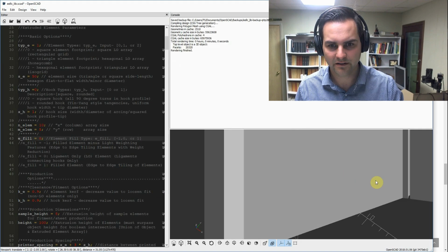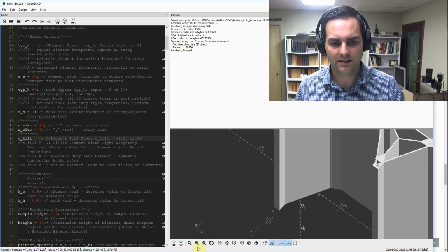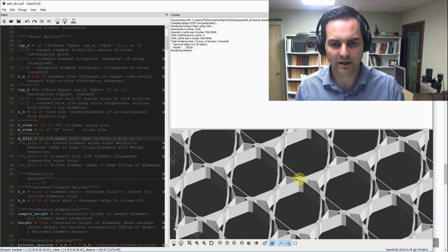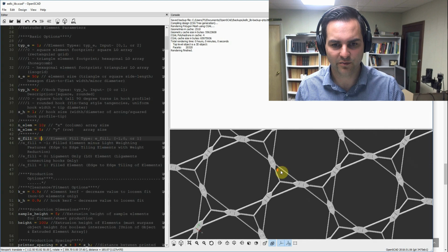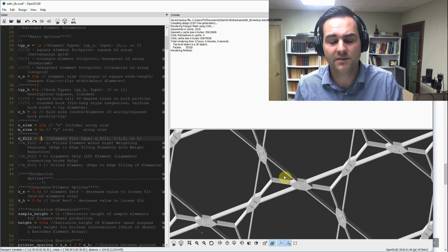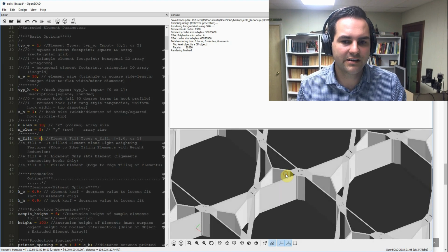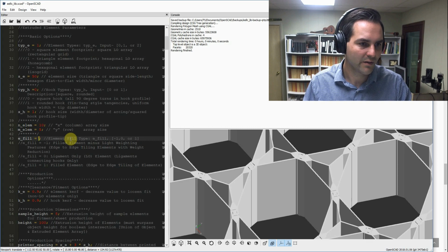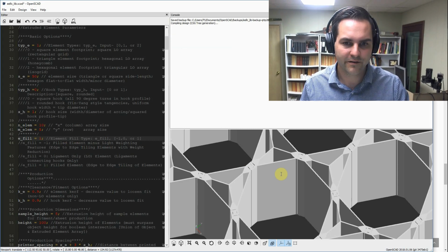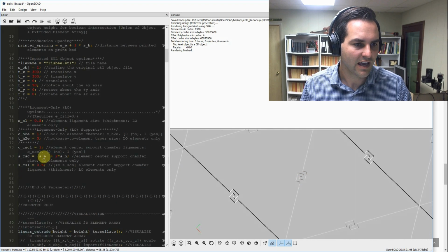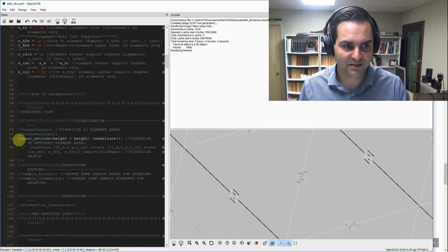Change that to 0. If I had these kinds of elements with ligament only, you don't worry about element kerfs because elements don't butt up against each other. So hook kerfs are all you need to worry about. Now you're ready to print if you're using a 3D printer. But in the case of a filled element, you'll want to manipulate the element kerfs and print some test elements.